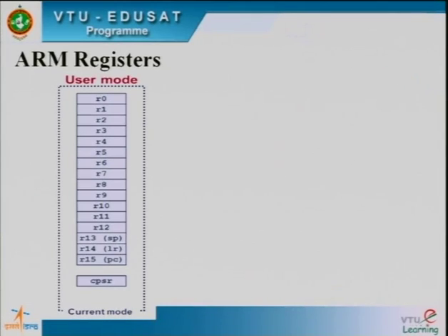So till now we discussed the various processor modes. So what are the different instruction sets available? We said 3 different instruction sets are available on the ARM family processors: normal mode, thumb mode, and Jazelle. Then we discussed all the different modes in which an ARM processor can operate: user mode, a non-privileged mode, and the privileged modes like fast interrupt, interrupts, and so on.